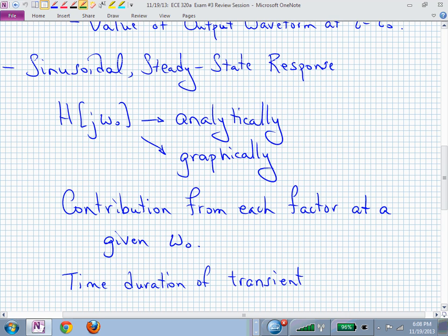Know what that means to sketch it in the S-plane, sketch your poles and zeros, and then show me what the magnitude and angle might be for the pole at s equal -2 minus j5. And maybe you're looking at a frequency of 7 radians per second. I'm hoping right now you're seeing this image of an S-domain plot.